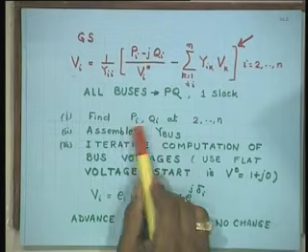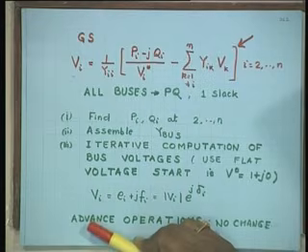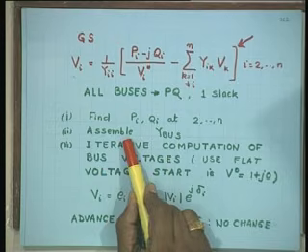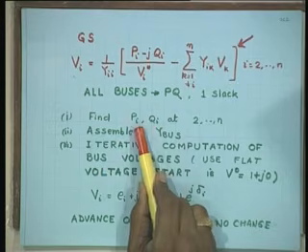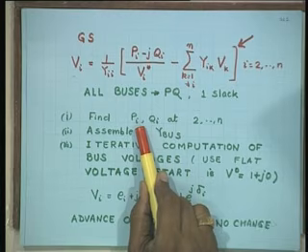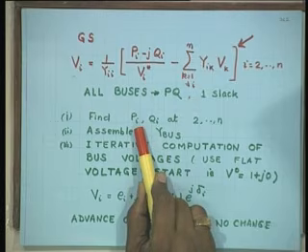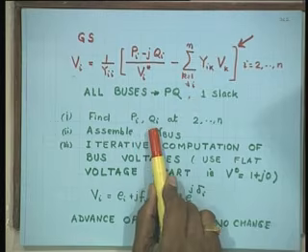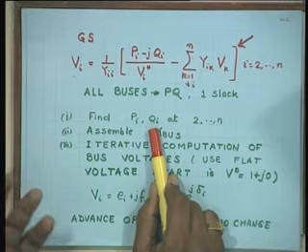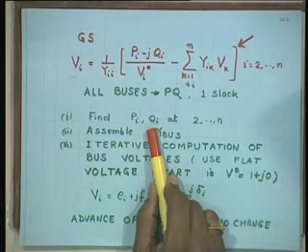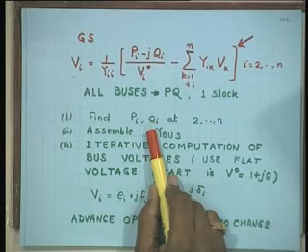Now, we find out Pi and Qi for i equal to 2 to n, that is, for n minus 1 equations. By find I mean, since you know load, since you know generation, generation minus load becomes Pi, in that sense find. Otherwise, they are supposed to be specified, but before specifying you have to find out from somewhere. Either you think or you get it from the old data for the system we closed yesterday. See, in a running power system, you do not have to worry about the initial starting solution, because it is already there.